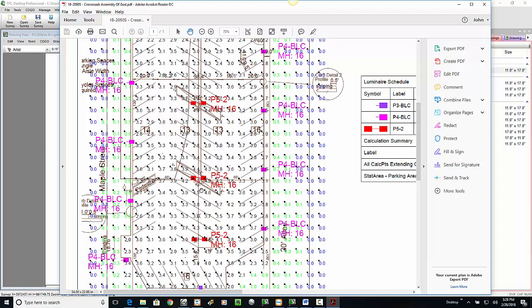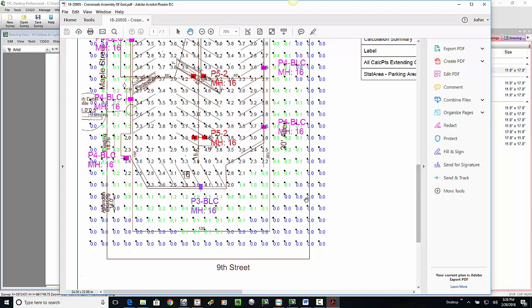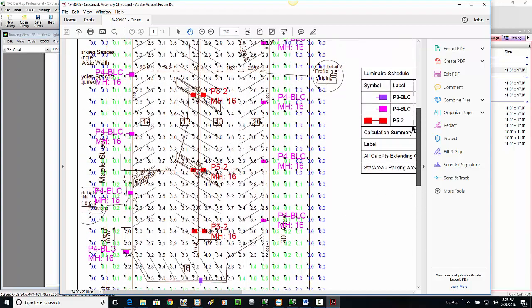They use those same lights that I was interested in using in those parking islands, dropped down to 16 feet, which is what the city is going to require. Then we need to put all the lighting around the outside to get the lumens that we need. And these are their lumen values. Within the parking area, we're a minimum of 2, a maximum of 5, so when we see a 3.8, 3.9, or 4.5, those are all reasonable values.